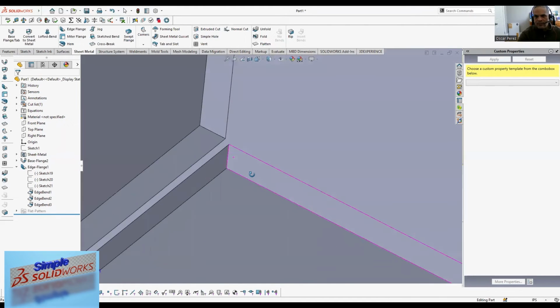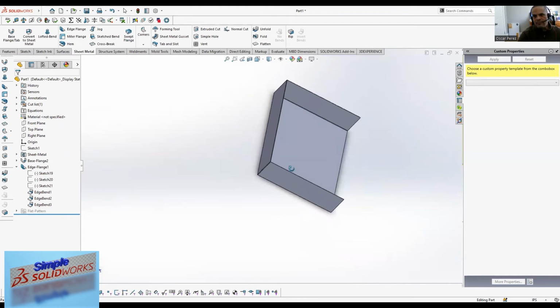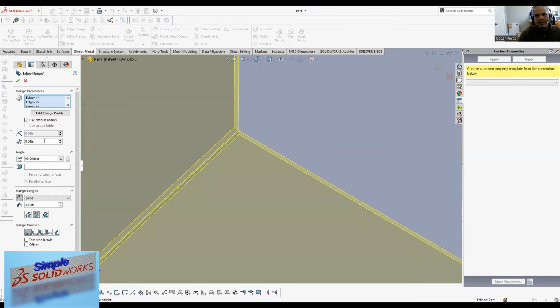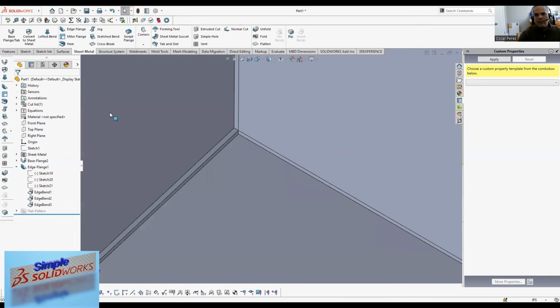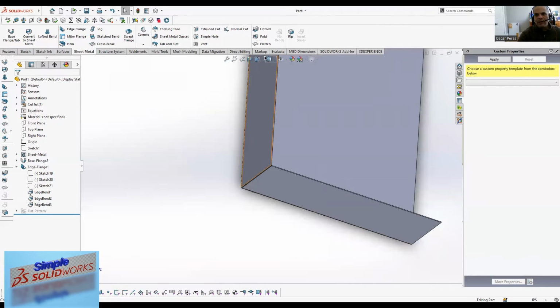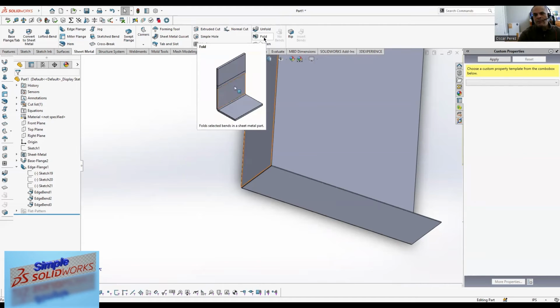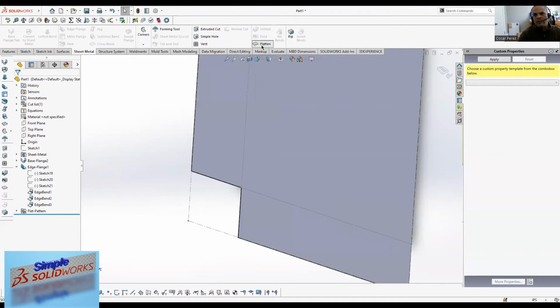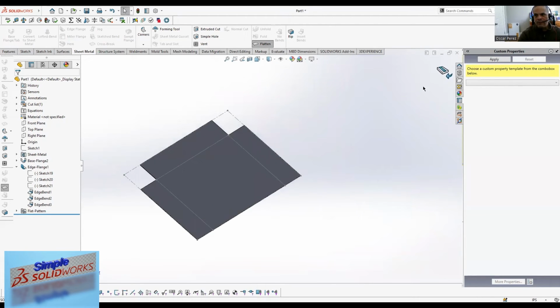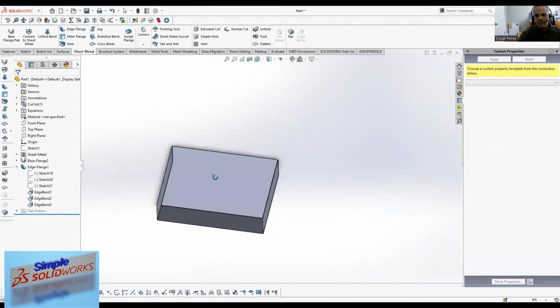All right. Still giving it that gap. See? Let's try that again. Let's give it 0.001 and see what happens. Okay, that's very close. That's as close as you're probably going to get as far as you flatten it. You come up here and you say unfold or fold or flatten. That's going to be more like if the part's made by some other program. So you have this icon up here, you just confirm that and you can just go back to being the way it was.